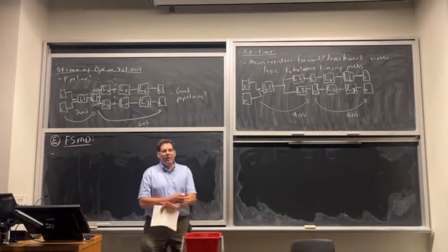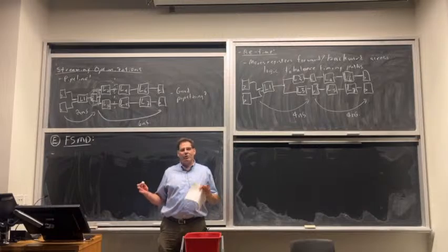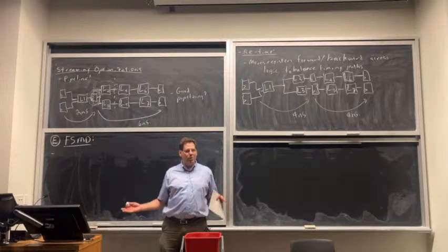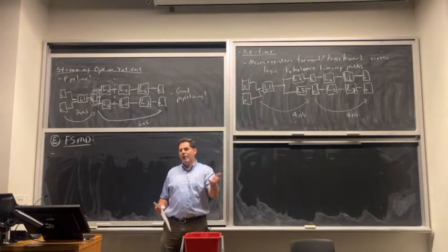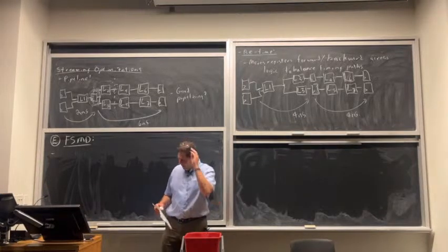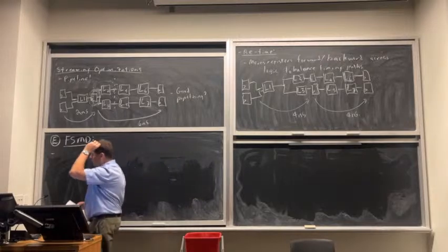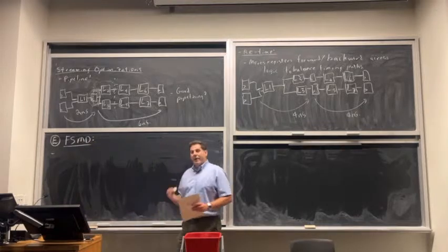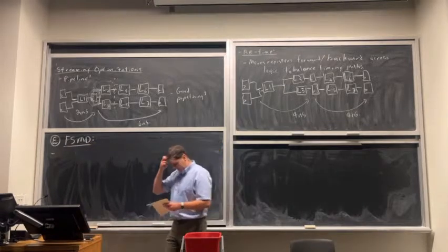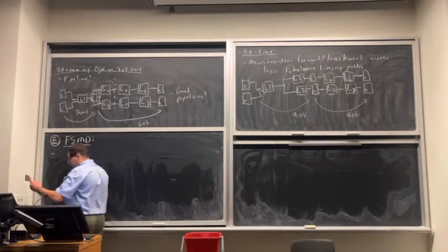In lab 1, we give you a basic stream circuit, just so you can learn Quartus and see how it functions. Then you're asked to optimize it: pipeline it and make it faster. And then we ask you to make what we call a shared operator version. A shared operator version is like a finite state machine with data. Let me show you what that looks like.